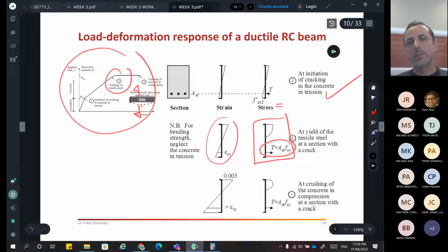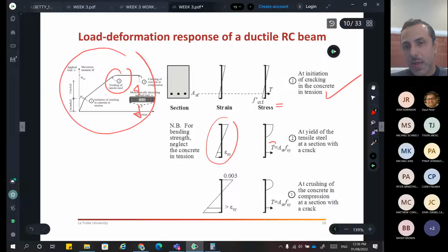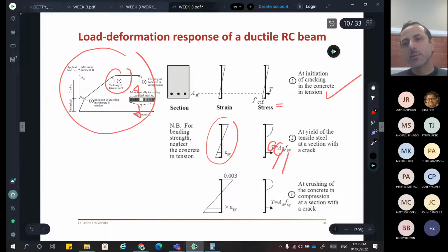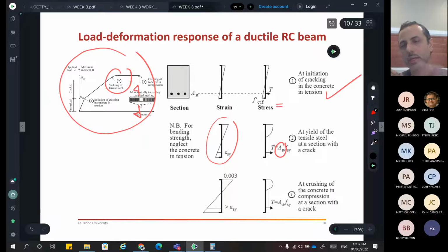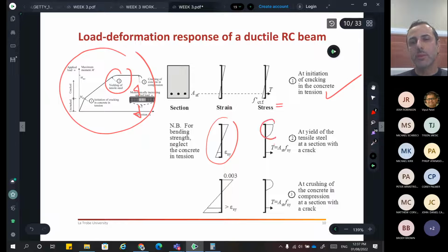And that's why, you're going to see this from first principles, we can always plot these things, right? So steel is under tension, and to find its value, the tension, simply what we did in mechanics of solids: multiply area by stress. The area is the area of steel. The stress is the 500 MPa. That's it. Now, as you're going to see in our design, sometimes we will ask you for the area of steel, so you just work it out differently. What about the compression? It's here. We're going to have a C component.